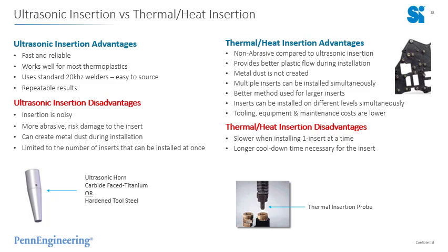Now, some of the disadvantages. It's very noisy. If you've been to a dentist office and you heard those ultrasonic machines, they can really bother your ears. It's the same with this. It's 10 times worse. It's more abrasive. You can risk damaging the insert itself. It creates metal dust during the installation. Sometimes that dust gets into the threads. And you're limited to the number of inserts that can be installed at any given time.